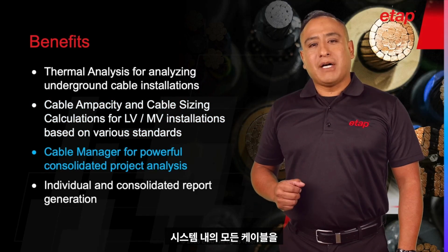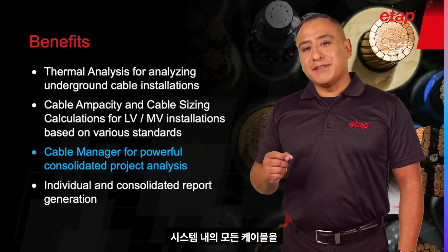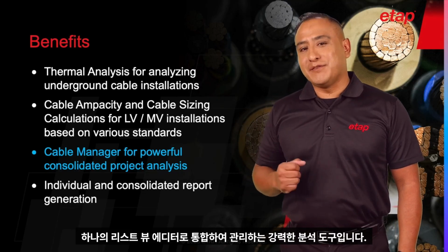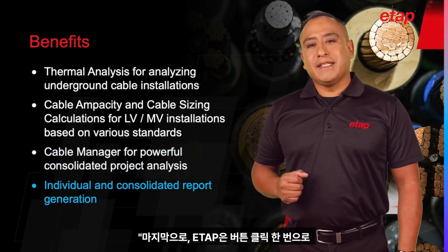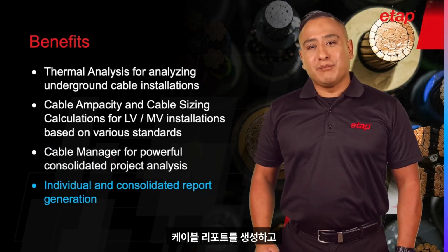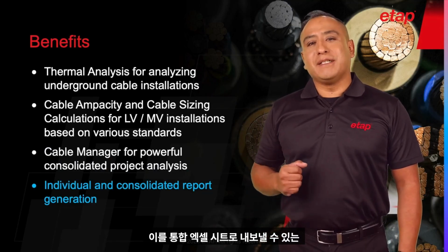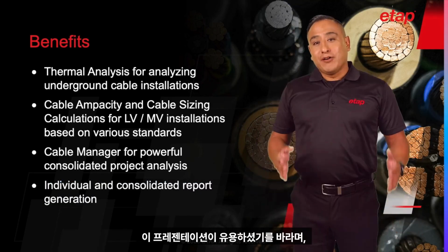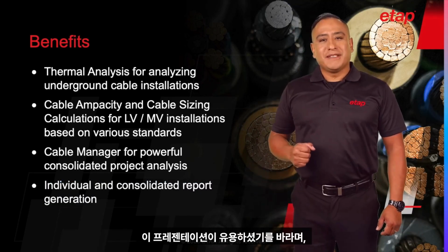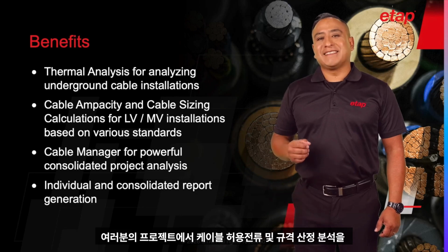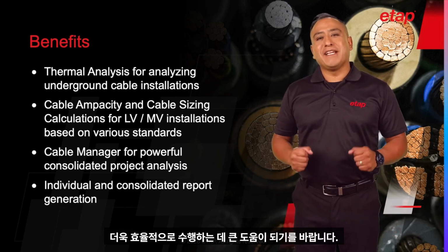The Cable Manager is a powerful analysis tool in which all the cables in the system are consolidated into a single editor in the list view. Finally, ETAP offers robust report generation capability in which cable reports can be generated through a click of a button and exported into a consolidated spreadsheet. I hope you found this presentation useful and that the tools presented today can assist you in performing cable ampacity and sizing analysis more efficiently in your projects.